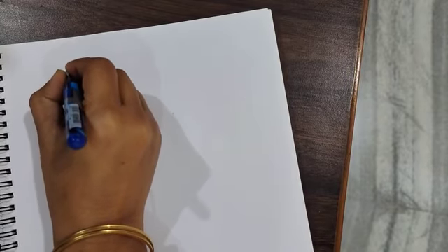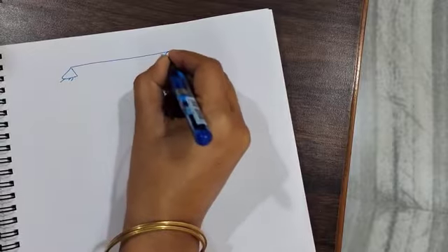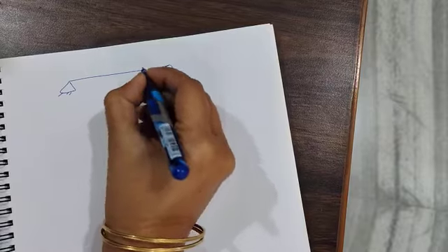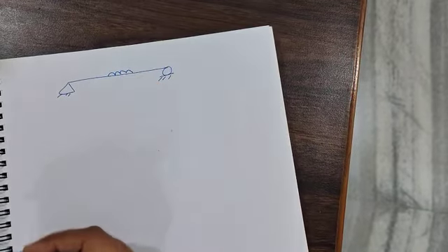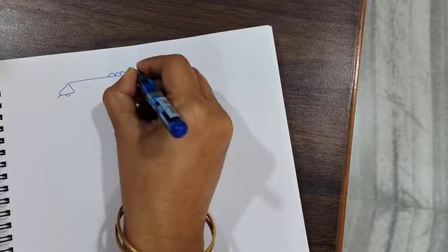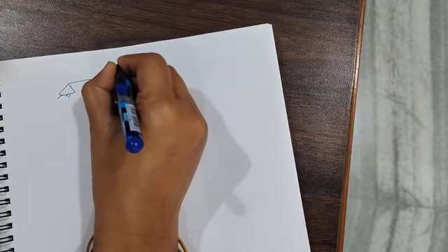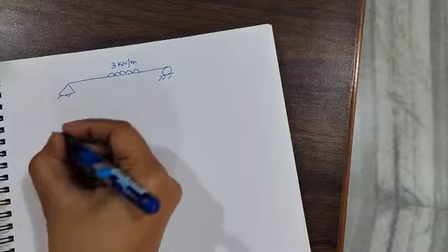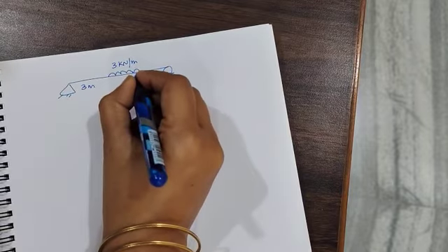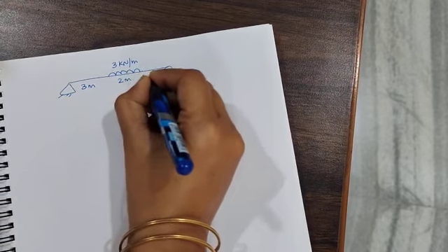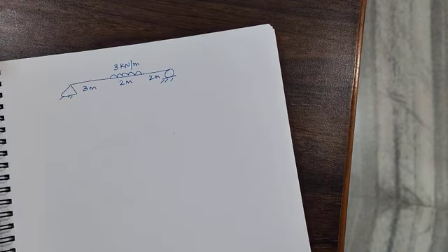Good morning, students. Let's talk about the development of shear force and bending moment diagram when there is a uniformly distributed load. I am directly starting off with the question in which, let us say you are having a simply supported beam. This beam is subjected to UDL, uniformly distributed load, upon some span. The value of UDL is 3 kilonewton per meter. This span is 3 meters, 2 meters and 2 meters. So the total span of the beam is 7 meters.